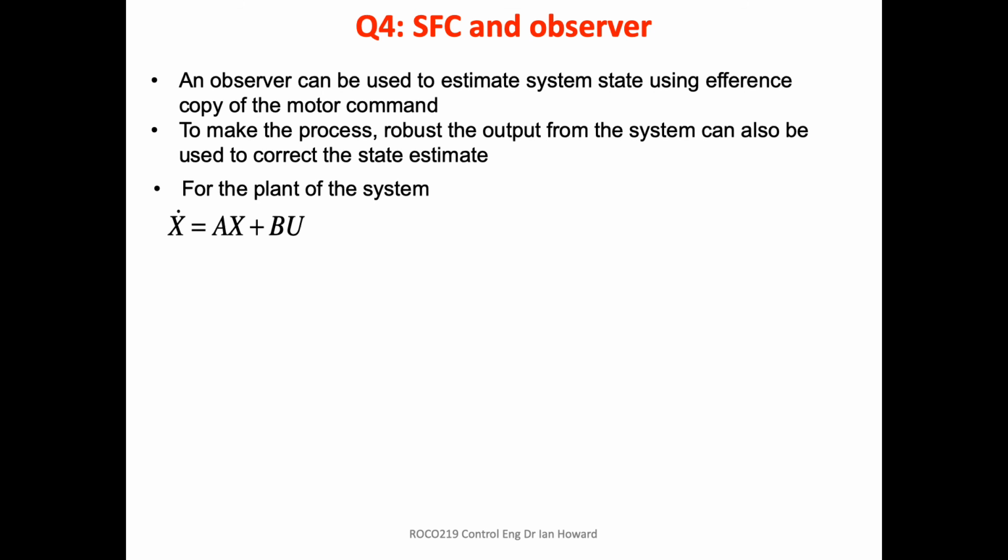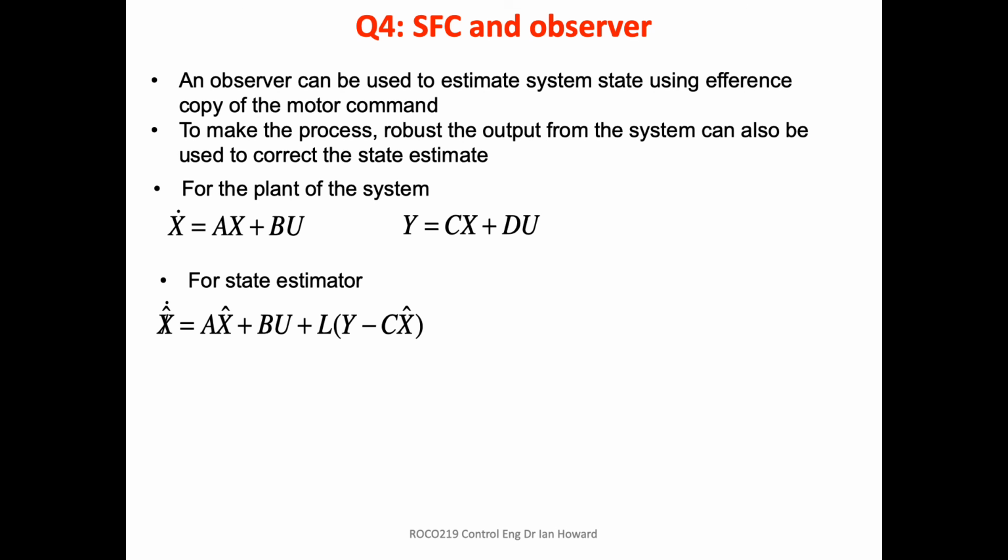Previously, from an open loop system, we've had the equation that the state x dot equals Ax plus Bu, but we have a slightly different formula for the predictor that we have now from the Luenberger, because what we have now is an estimate of the state. We're not saying it's the actual state. The actual state is x. We're going to call the predicted state x hat. So we have an updated equation now that x hat dot equals A x hat plus Bu.